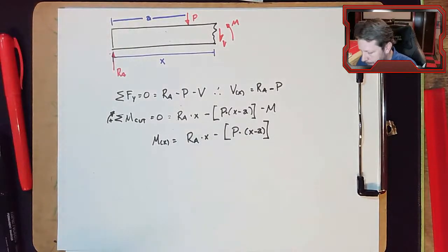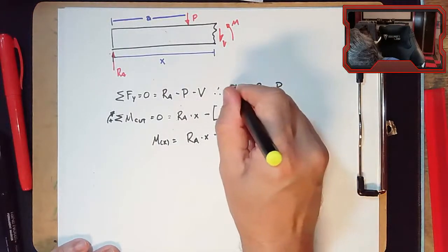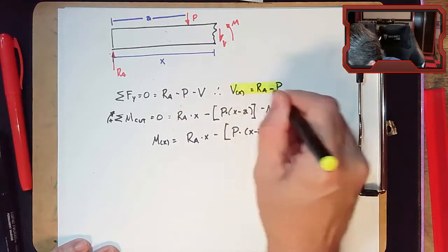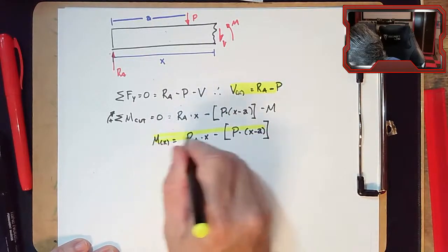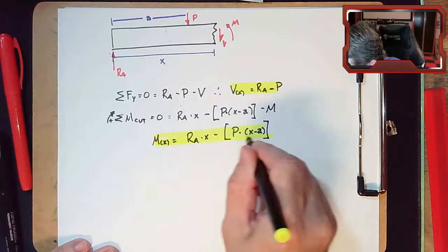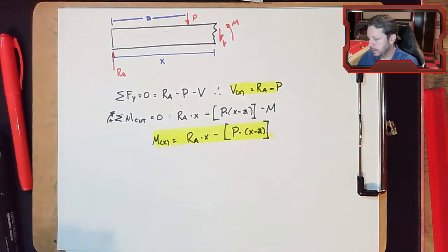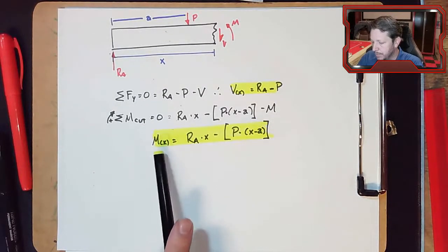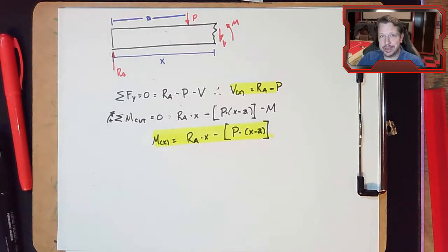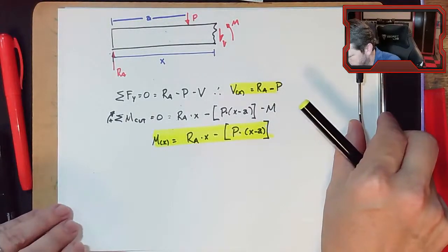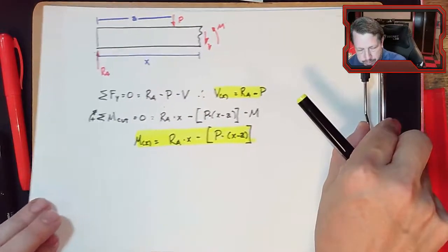At this point, it's a very simple beam. It just had one point load and was simply supported. But you could at least start to see where, if you wanted to, you could develop these equations and then take some derivatives, find the inflection points, and figure out where the maximum moment is. We're going to do that next time, but in a graphical way without actually having to do the derivatives. Let's do one more of these with a distributed load on it, just to reinforce the point.